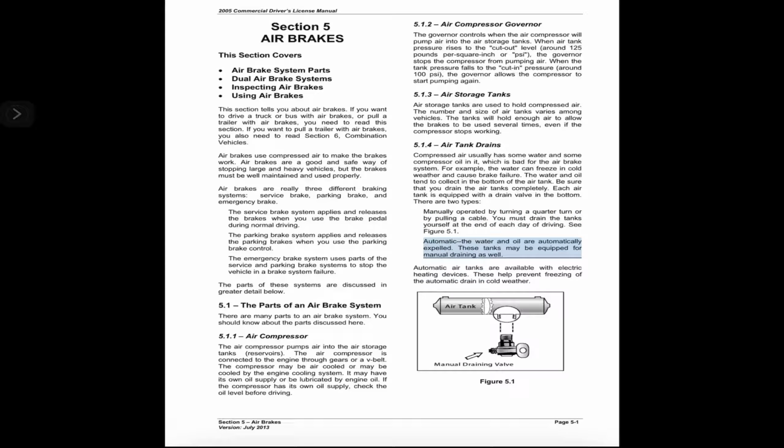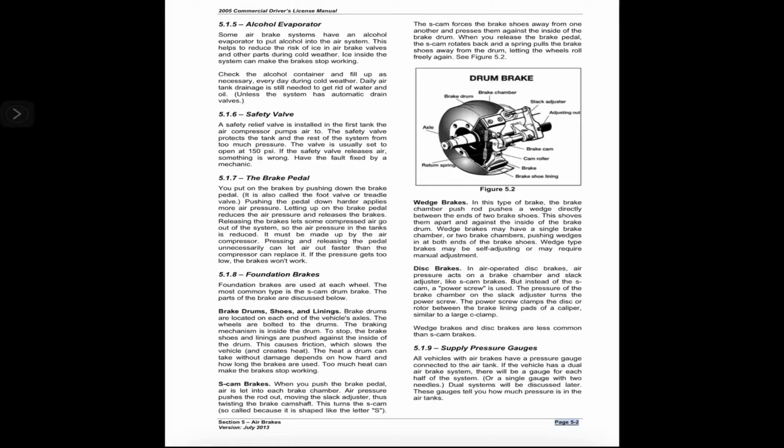See Figure 5.1. Automatic: the water and oil are automatically expelled. These tanks may be equipped for manual draining as well. Automatic air tanks are available with electric heating devices. These help prevent freezing of the automatic drain in cold weather. Figure 5.1.